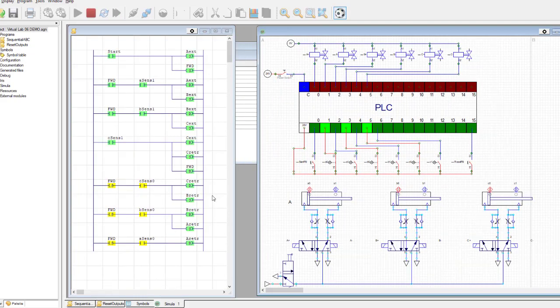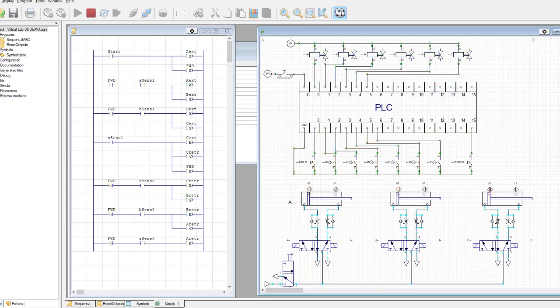So there's a basic problem with this, which is that you notice that the not forward bit is true here, and so it could potentially make one of these outputs, the retract outputs, go true. So what we're going to do is, instead of using forward here and not forward here, we're going to use an actual separate bit called reverse, and it's only going to be true during this reverse cycle. So let's turn off dynamic display.